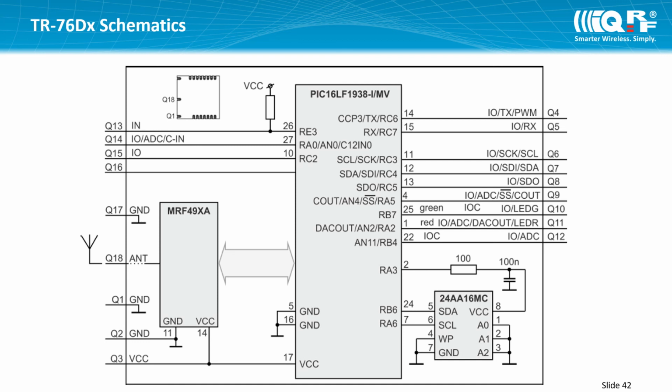The TR-76D module, intended for soldering, has no pins connected in parallel, but all are available on the soldering pads, including pins controlling LEDs. So a user can design the device with LEDs visible on the box. The usage of LEDs is strongly recommended because of the operating system, and also the DPA uses some system indication, for example bonded or unbonded state, factory reset, TR programming, and so on.